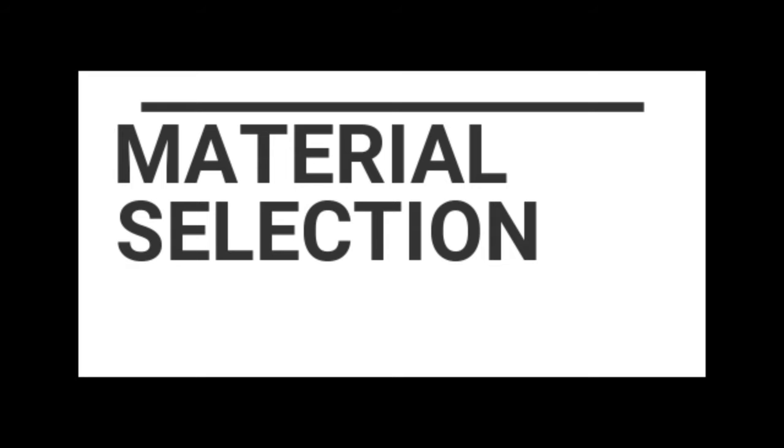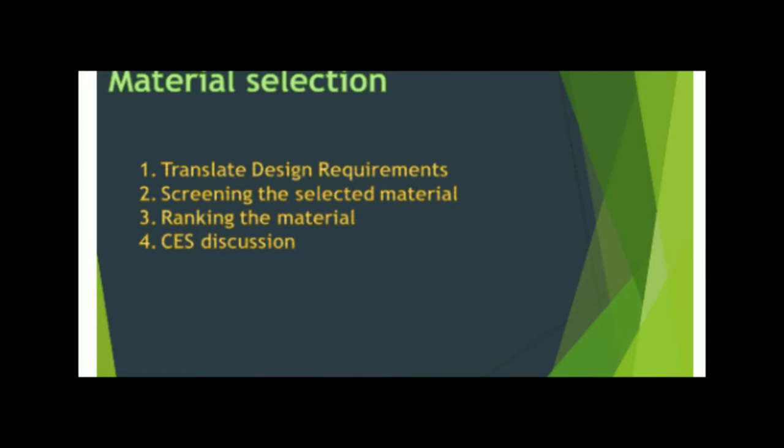For material selection, there are steps we use. First, translate the design requirement. Second, screen the selected material. Third, rank the material. And fourth, we use the CES EduPack.